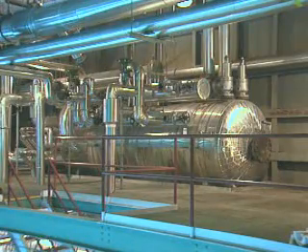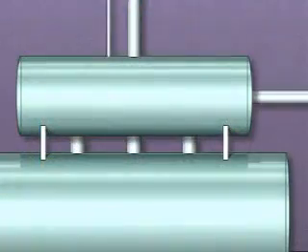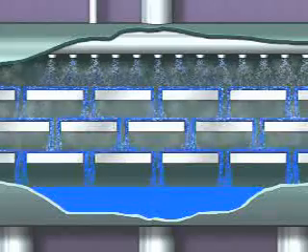The deaerator heats condensate and also helps remove air and non-condensable gases that can cause corrosion. As this cutaway illustration shows, unlike a shell and tube heat exchanger, the deaerator is an open or direct contact heater. That is, condensate is heated when extraction steam and condensate contact each other and mix in the deaerator.